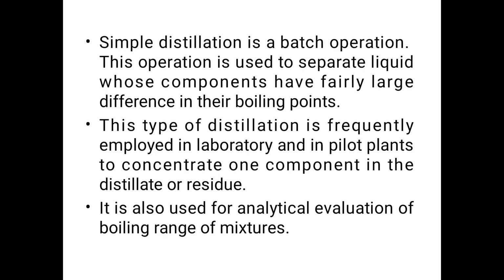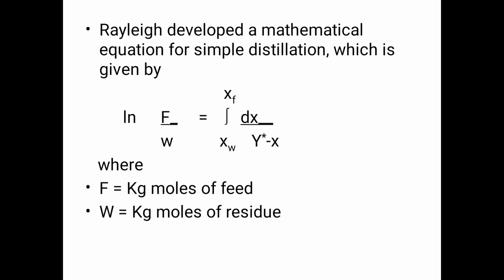This type of distillation is frequently employed in laboratory and pilot plants to concentrate one component in the distillate or residue. So, distillate having the more volatile component is the top product of the distillation column, and residue is the bottom product, having the less volatile component. It is also used for analytical evaluation of the boiling range of mixtures. We already said that Rayleigh's equation is very important for calculating the simple distillation process.